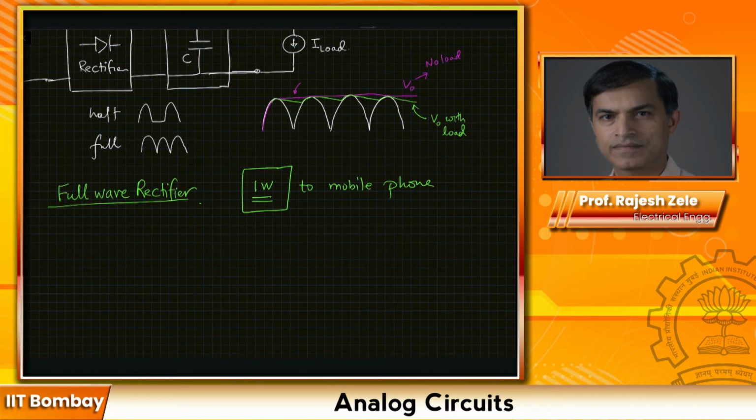One of the numbers will say 100 volts to 230 volts. What that means is this charger can be used anywhere worldwide. It can be used in the United States, in India, in any other country, because generally the AC voltage ranges from 100 volts all the way to a maximum of 230 or 250 volts.